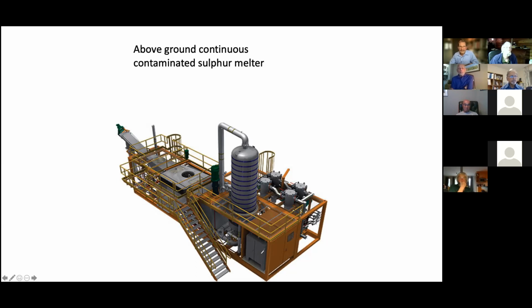So if you have gravel, so on and so forth, everything settles down to the bottom, and there is a continuously moving auger. As opposed to the last process, this is a continuous removal of the sludge, of the sediment, of the gravel, whatever. And it goes into a pump tank that pumps the sulfur into this heat exchanger. It's a vertical shell and tube, so you have no issues with any plugging of the tubes or anything at a very high velocity.